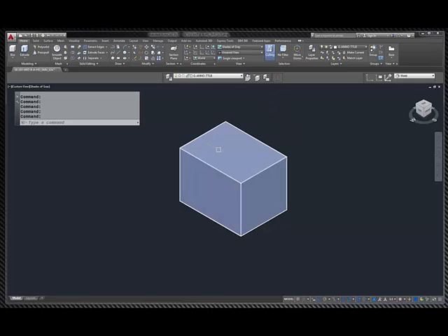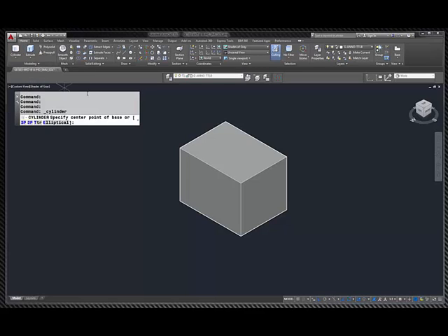Okay, so I want to draw on the different sides of this cube. So I'm going to go up here to my box again, but this time I'm going to click on the down arrow and look what we have here. We have cylinder, cone, sphere, pyramid, wedge, and torus. Well, I'm going to pick cylinder for right now, and I'm going to come over here, and I can draw anywhere on this plane and notice it went from world to unnamed. I can go back and click on world, but when it's unnamed, it has to do with picking the side. Notice it changed.